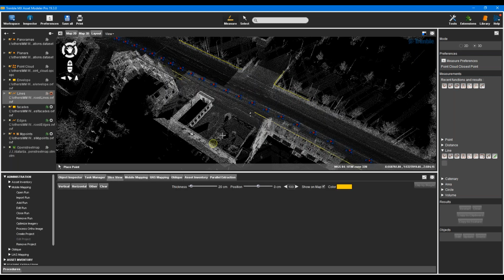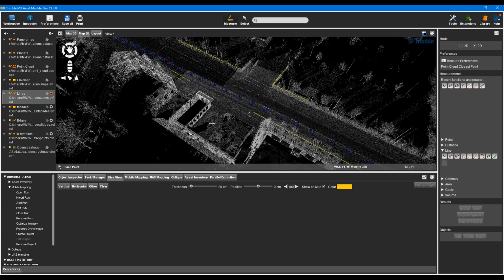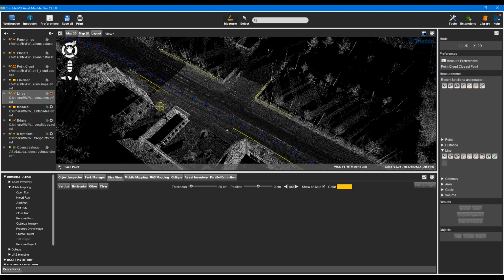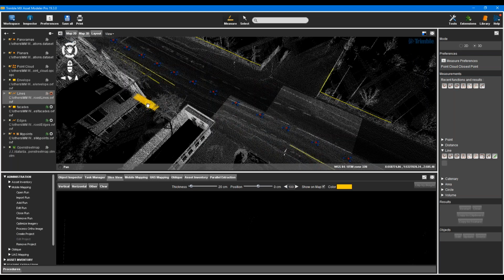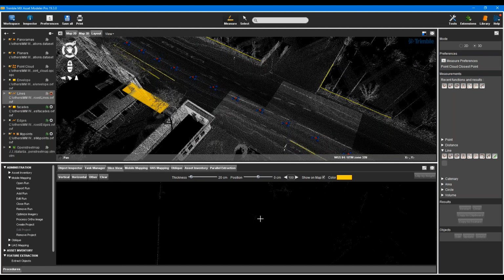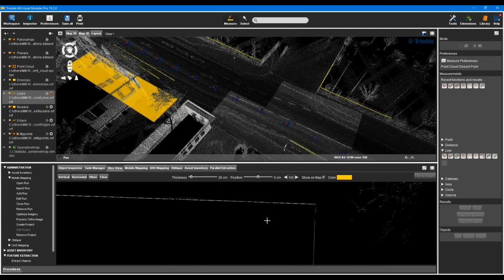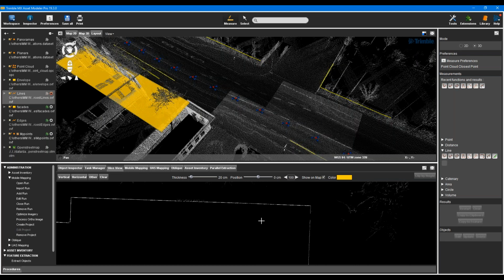To define a slice view, only a click is needed, and it will create a perfect slice horizontally to the ground. This is the benefit of extracting features using the slice view, because you will have the same horizontal level for the extracted features, which could be very useful for the footprints of buildings, especially for those buildings where the walls are not clearly seen in the top view.